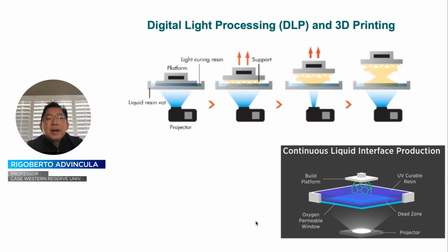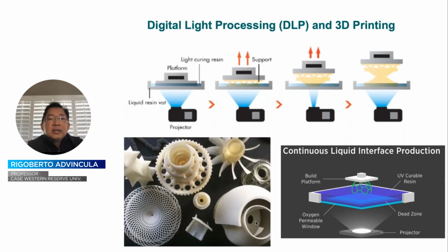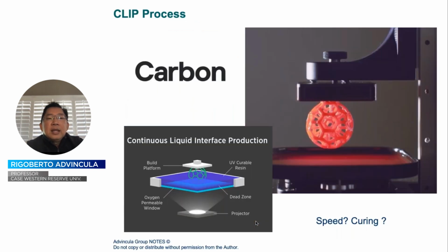In other words, it is possible that by controlling quantitatively the amount of quenching species, one can limit the polymerization very much near at the surface. The result is DLP SLA is really one of the best ways to obtain high resolution 3D printed materials and a wide variety of resin compositions that can be used in the industry. Now, the discussion about the speed, discussion about the prototyping versus production is another matter.